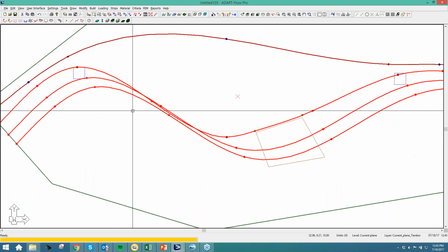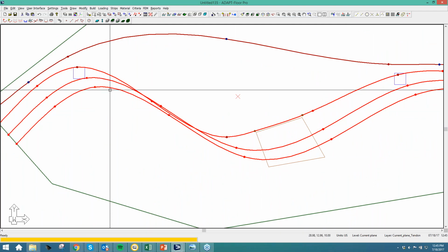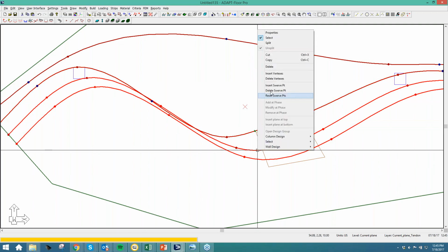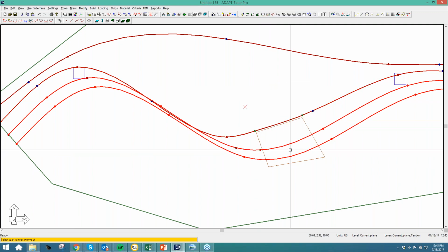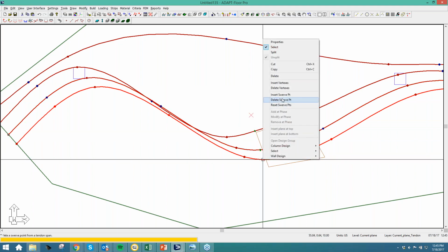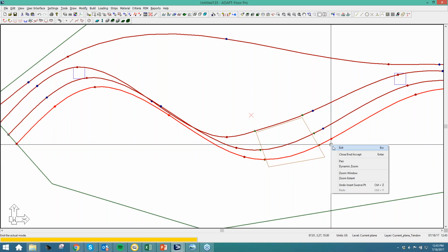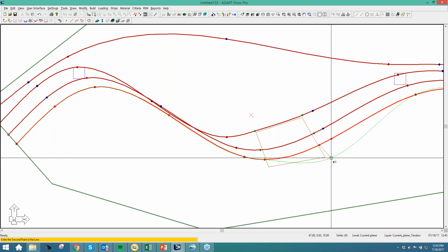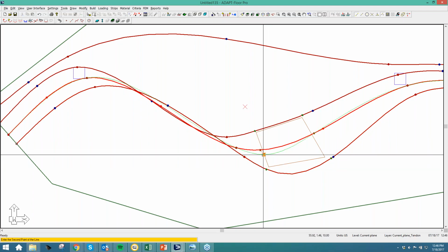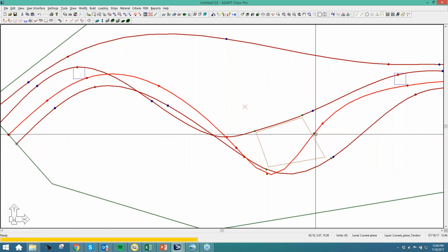And what's beautiful about this is that I have a tendon curvature already, right? There's a profile vertically of this tendon, and by me assigning these swerve points, I am not changing that profile at all. I'm just simply moving this in plan. So the horizontal curvature will respect the vertical profile that's already been established. All right, again, just moving this guy over here.